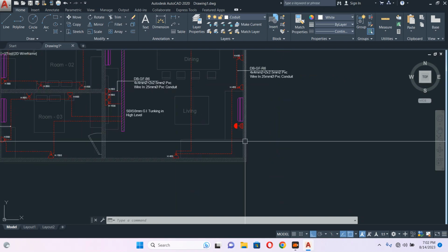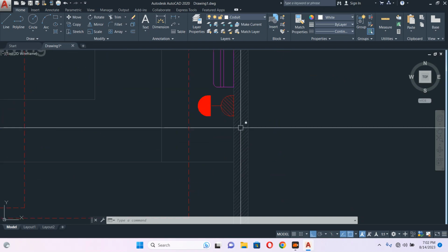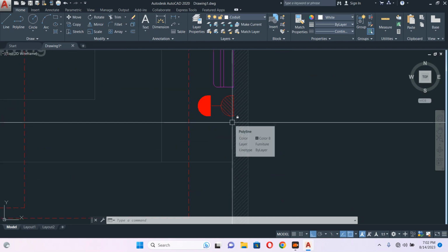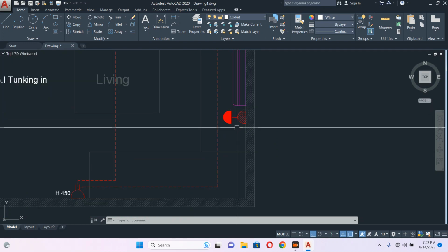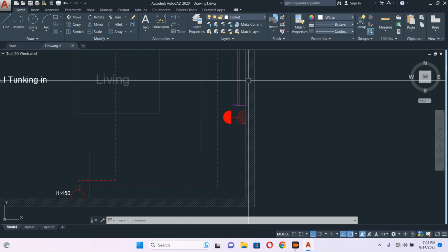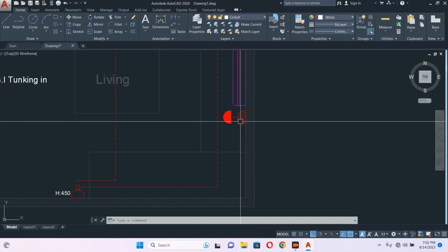So keep in your mind: the device ampere can go higher, but it should not go lower than the breaker in the DB. You should keep it in your mind. That one is very important, and I will tell you how the AC connection will be.